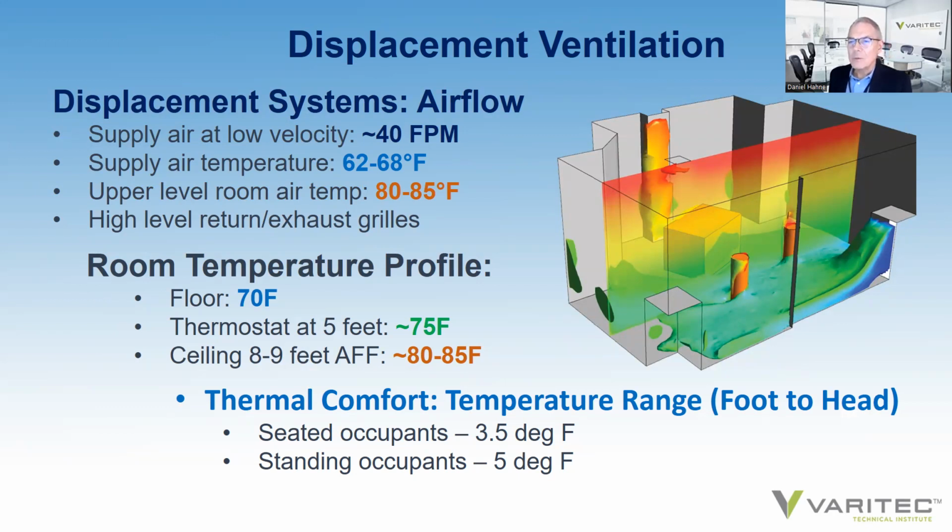People can ask, well, won't people notice their feet are cold and their head warm? No, providing the temperature differential from the floor to the 6 foot height of the occupant doesn't exceed 5 degrees for a standing occupant, or if you're using this excellent solution for an auditorium, then it would be 3.5 degrees for a seated occupant, temperature differential from the foot to the head. So if you stay in this range, then you won't have thermal comfort complaints.